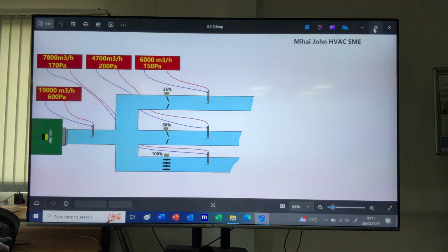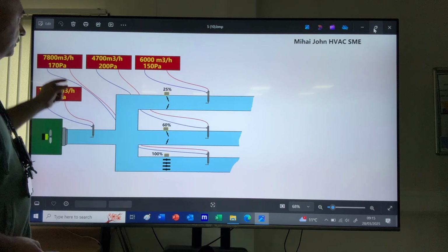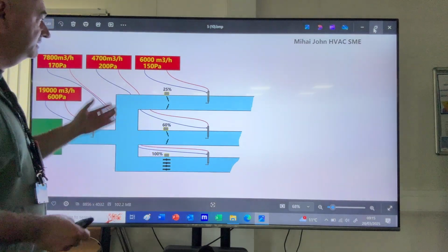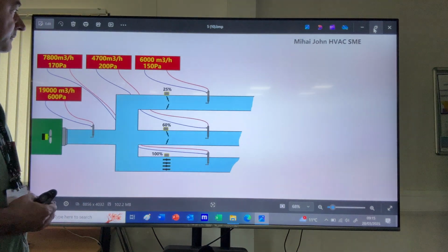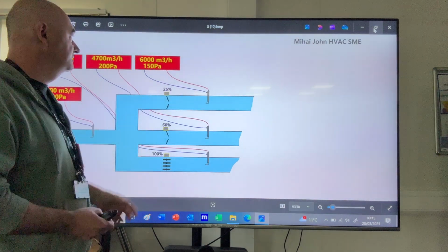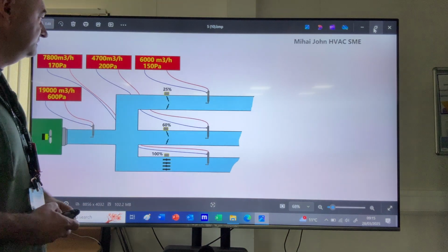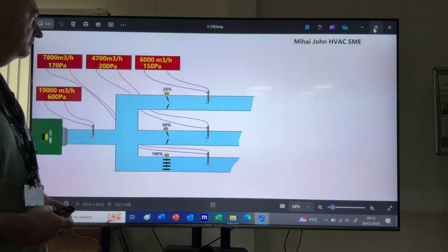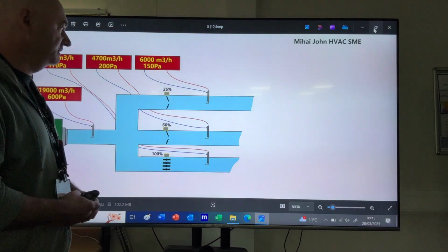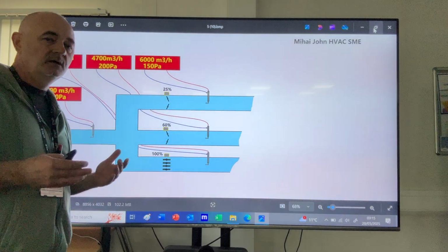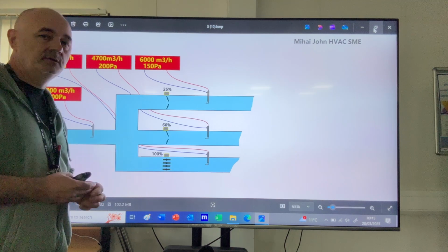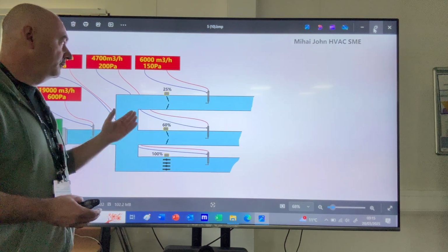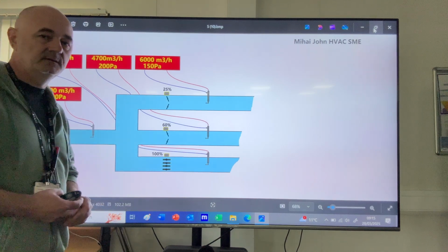Some units have automatic dampers where I can read the global airflow. Also, I can read the airflow in the branches which go into the room. This is a better system. It uses a pitot tube, as I explained before, sending the data to these DPMs, and then the DPMs control the quantity of air which passes by, but they are validated to be put in manual mode. So I can use the automatic function only when I'm balancing the system during a shutdown.